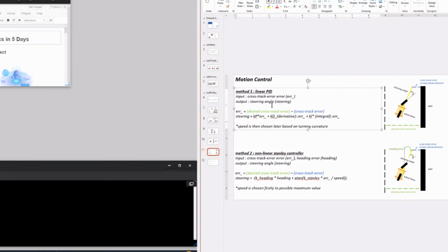And the linear PID method here, a classical method, works pretty well, because I have a proportional coefficient here and an integral coefficient here to keep the robot balanced, even if we have some noise in the laser scan measuring.